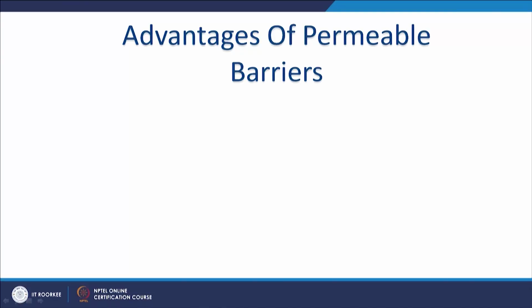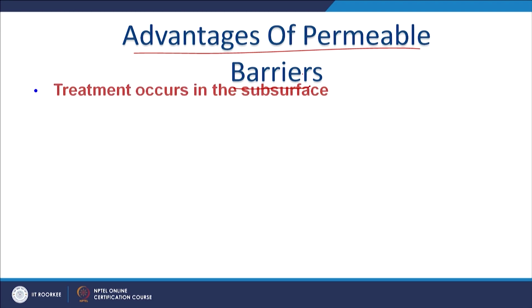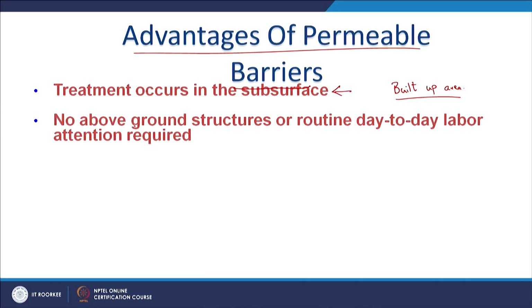So moving on, what are the advantages of PRBs, right? So let's look at some of these aspects. Treatment occurs in the subsurface, that's something we looked at, because let's say if you have considerable built up area, and if the land costs are relatively high, that's going to be remarkably worthwhile in that context. Operation and maintenance costs are relatively low, remarkably low, because it's a passive technique, and no above ground structures are required and no labor costs or such, right.